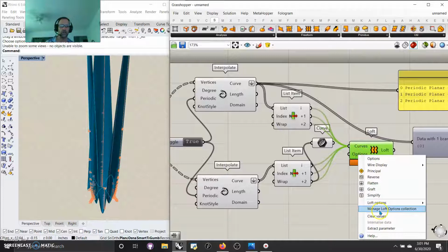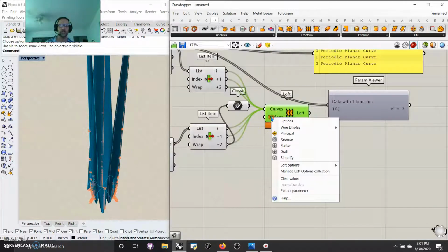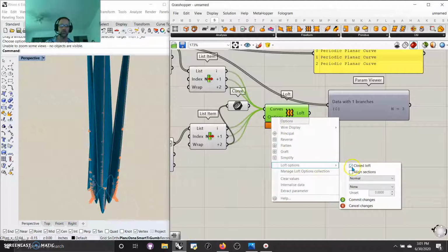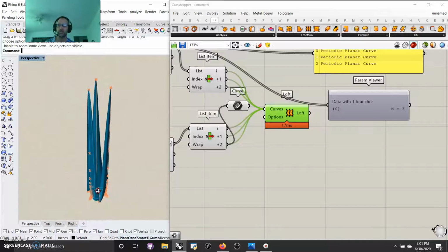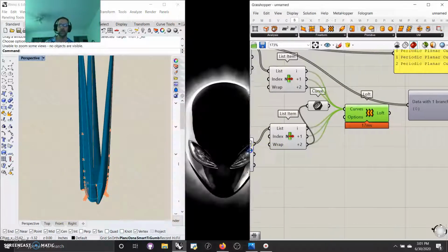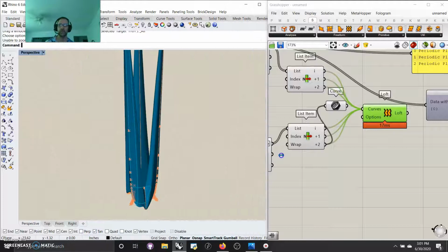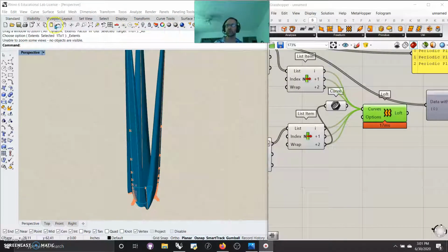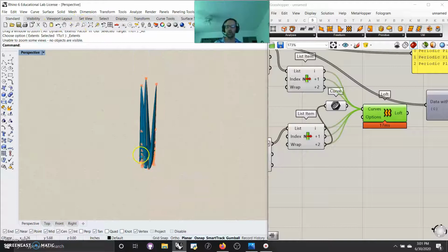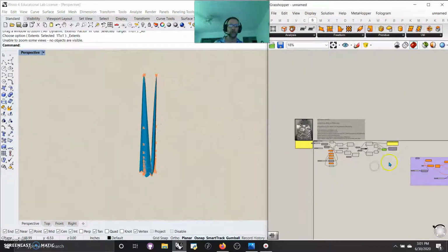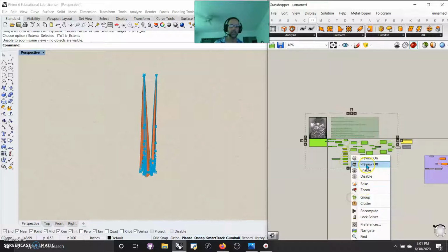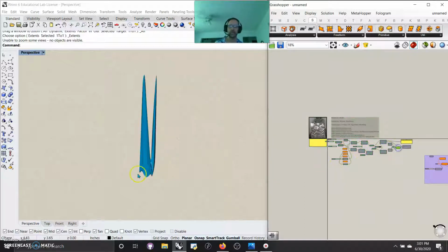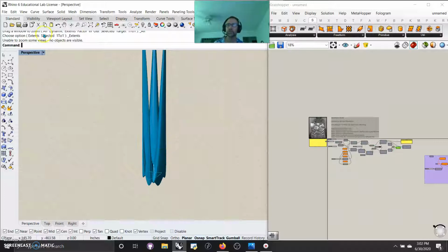I could go in to close it under loft items. That's a pretty necessary thing to do. Close the loft, and I will align things so they run very nicely. You see how it smoothed itself out. Now I have a geometry. I'm going to shrink. I'm going to bring it back here. I'm going to take my picture over here. I'm going to go to Standard, View All, zoom in, and say, okay, there's something. And in zooming out here, I'm going to lose track of seeing everything but that final object. I'll take that all off preview, so I'm only looking at that final object. And there it is. It's a pretty interesting device.